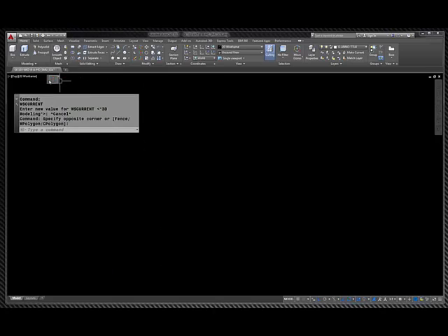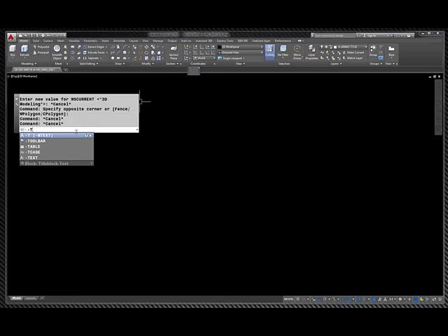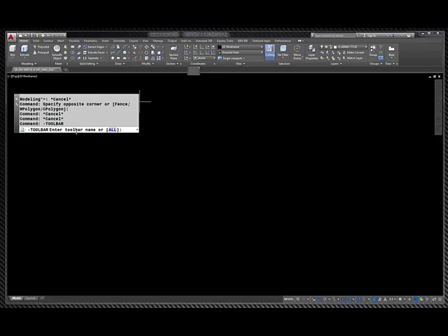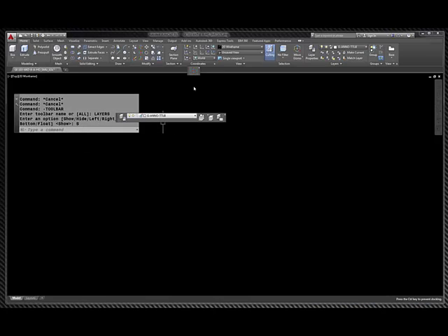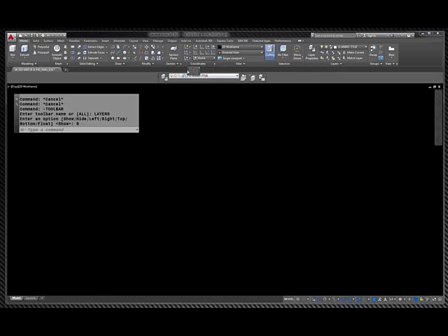Here is my toolbar. I'm going to park it right up here, and if I hover over it, it should say Doug's 3D toolbar. We had that in a previous video. I'm going to create some toolbars. Since I have a toolbar here, I can either use that or I can go to my toolbar command. So hyphen toolbar, enter, and then layers, enter, S for show. And there is the layers toolbar. I'm going to take that and park it right up here. There we go. And I'll put mine somewhere on either side of it here.